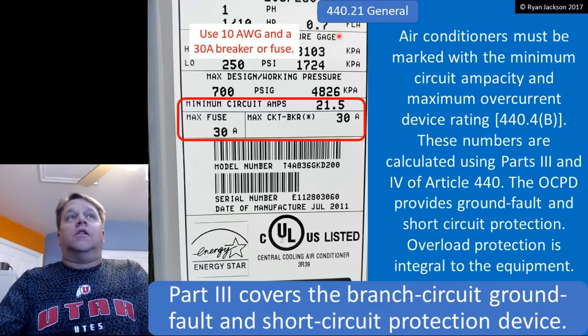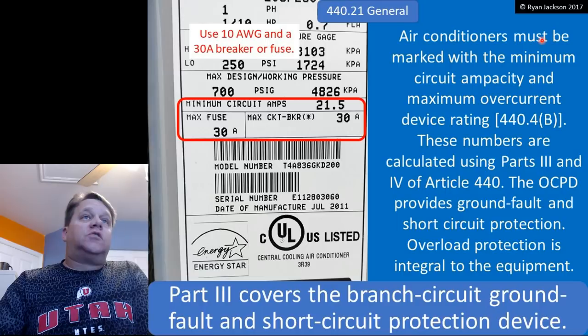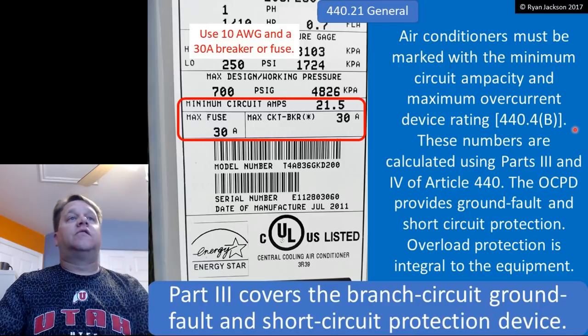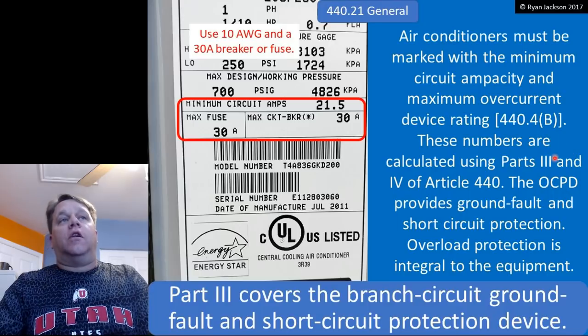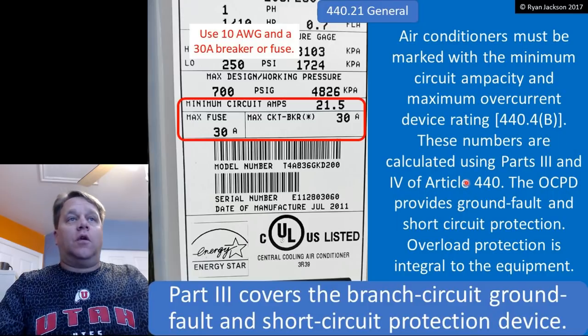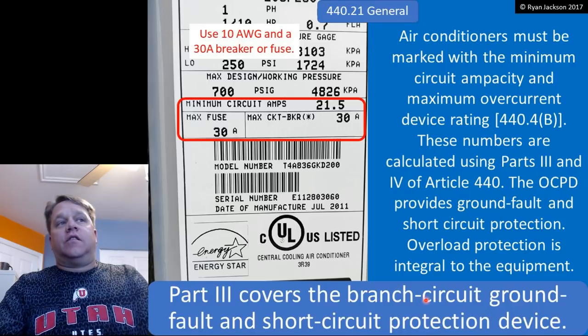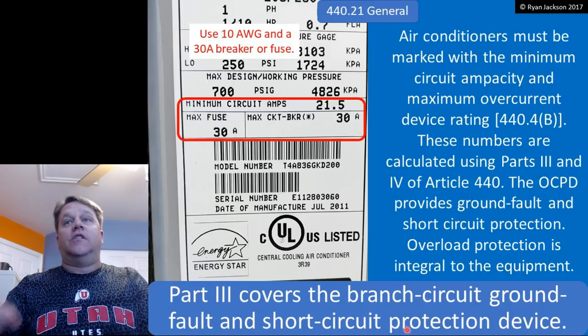But a lot of people want to know this, so air conditioners must be marked with the minimum circuit ampacity and the maximum overcurrent device. These numbers are calculated using Part 3 and Part 4 of Article 440, 440.21 for the branch circuit, ground fault, and short circuit protection device, so the fuse or breaker.